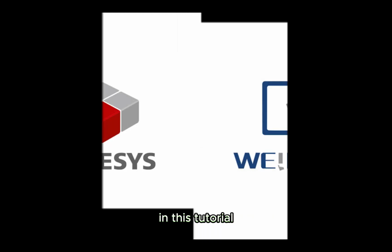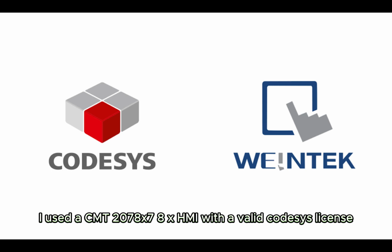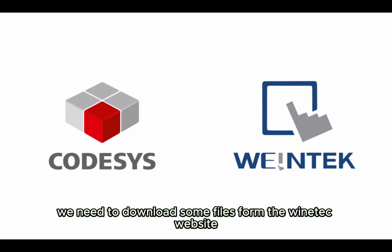In this tutorial, we are going to configure a Weintek HMI to work as a controller using CODESYS. I used a CMT278X HMI with a valid CODESYS license. In order to make things work, we need to download some files from the Weintek website.